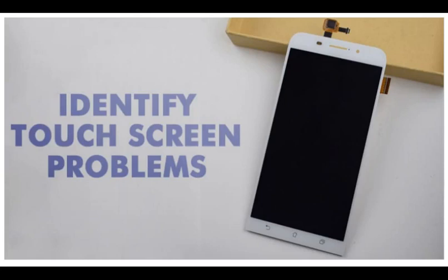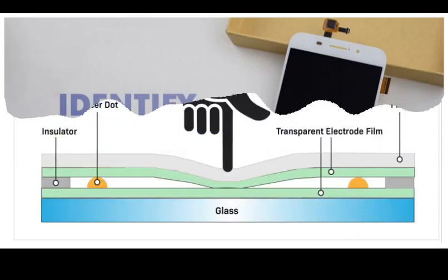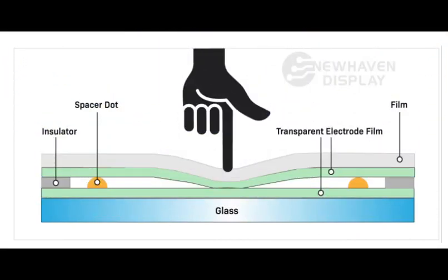Advantages: excellent image clarity. More resistant to scratching than resistive. Resistant to surface contaminants and liquids, dust, oil, grease, moisture. Multi-touch, 2 or more touch points. Disadvantages. Sensitive to EMI/RFI. Must be activated via exposed finger, or thin surgical or cotton gloves.